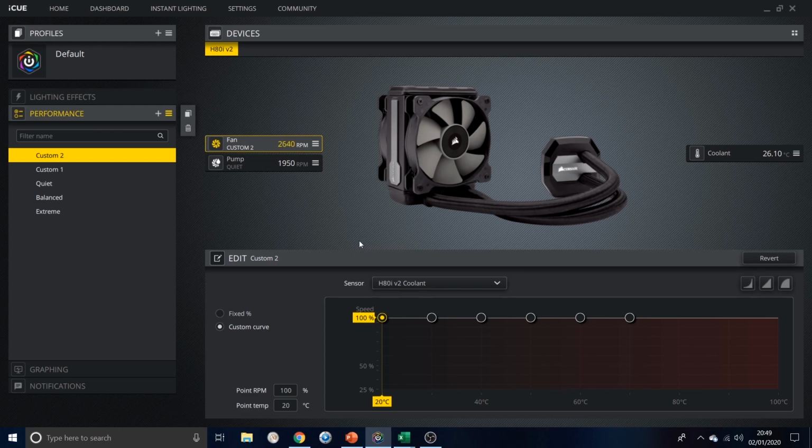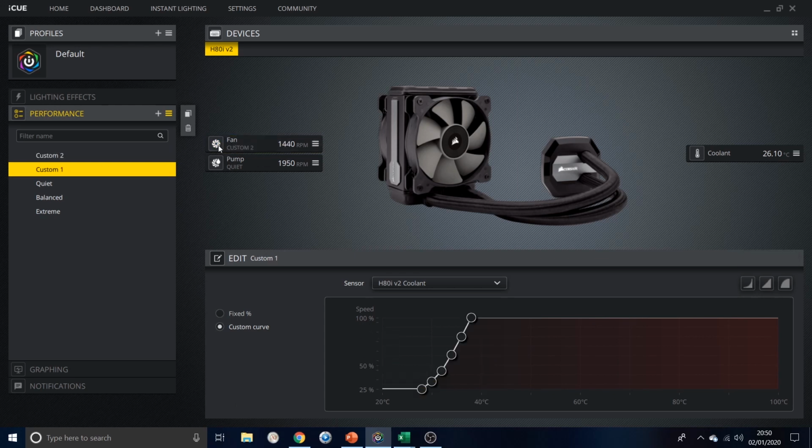That's now us in control of the fan, taking manual control of it. And that's great, because I can use that to change the fan speed to different levels, and then run the fan at, say, I think 46%. So 46% of the maximum speed will now converge down onto a new value here, and it looks like about 1,500 RPM. Well, I don't know, we'd need to take an average on that figure, but anyway, you can adjust the percentage of the fan speed as a function of maximum, from 100% down to 25%, and that's the beauty of this custom system. So I'm just going to put this back onto custom 1, which is my custom cooling curve.